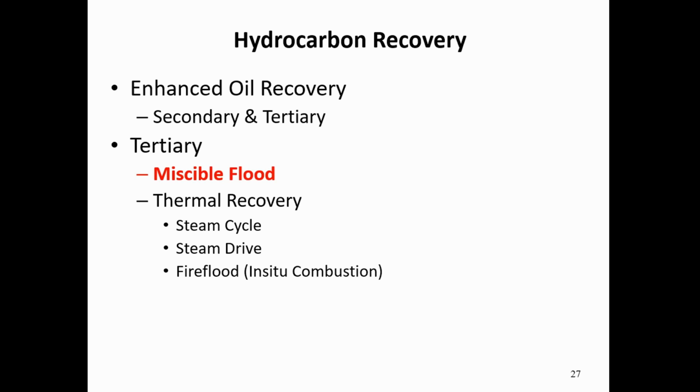Will every gas be miscible in oil? The answer is yes, including nitrogen. But when will the gas be miscible in oil? If the injection pressure of that gas is more than what we call MMP, minimum miscibility pressure.